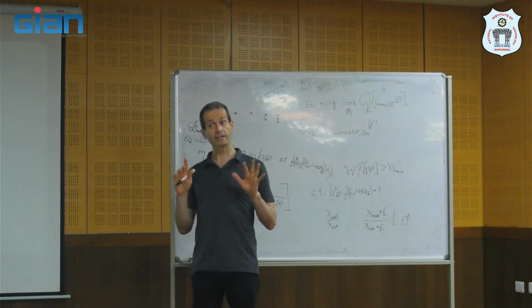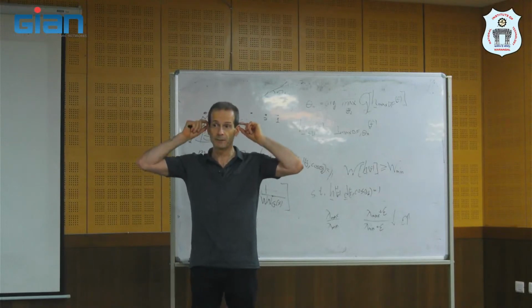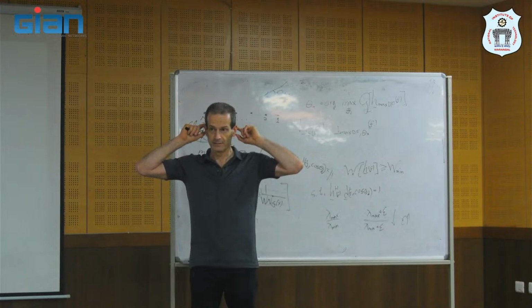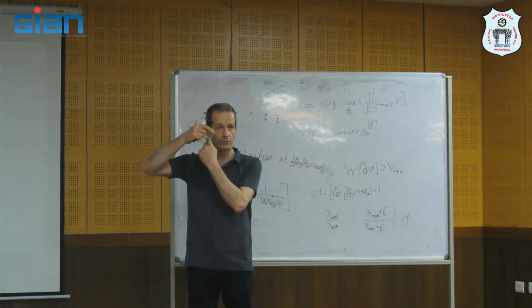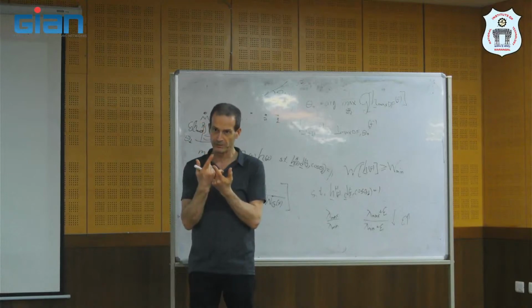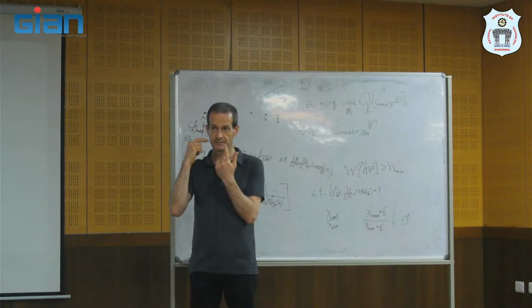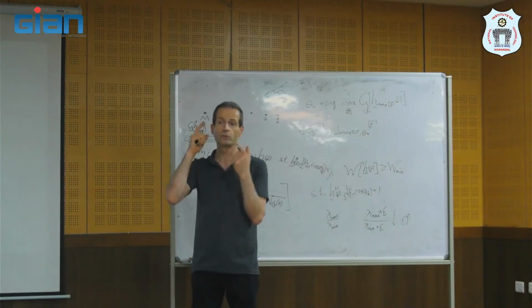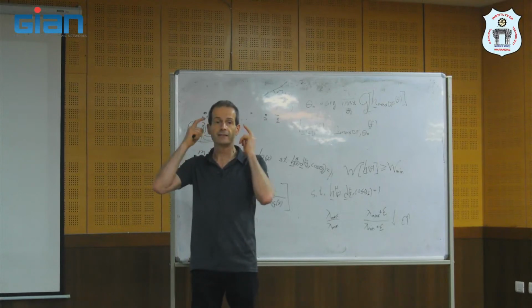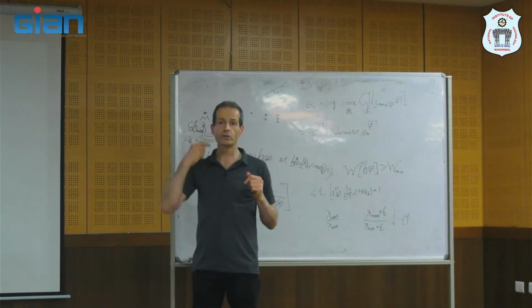Let's think. Smart glasses have microphones, and they also have loudspeakers here. I don't want to get feedback of the loudspeaker at the output of the beamformer. So I will add nulls in the directions of the loudspeakers, where the signals come from, so I don't get feedback.